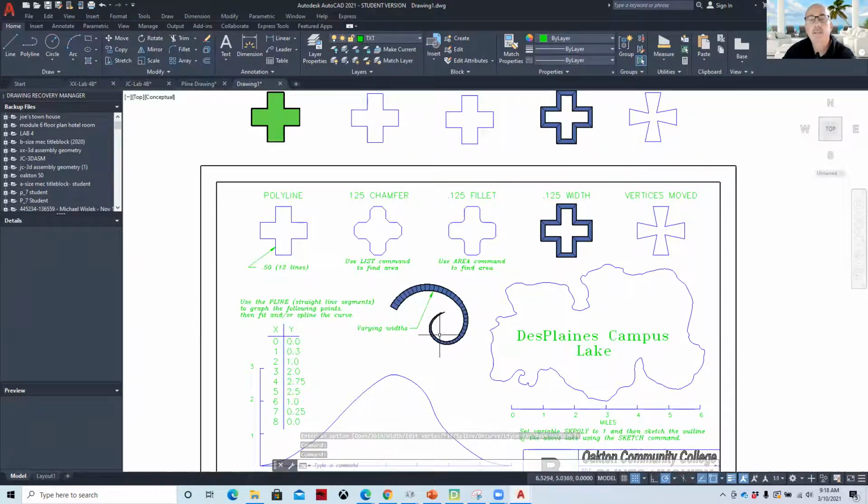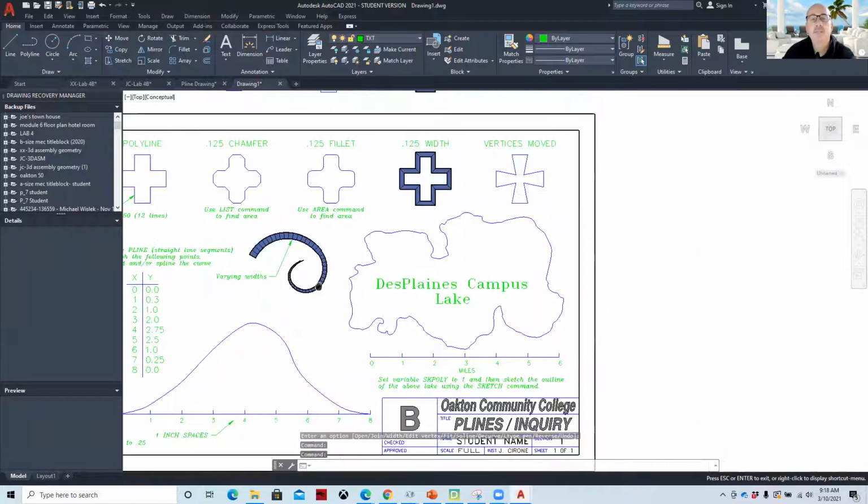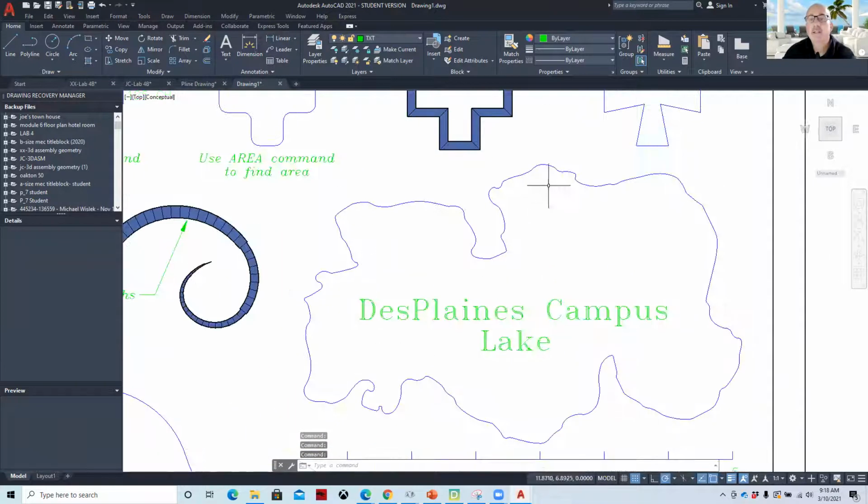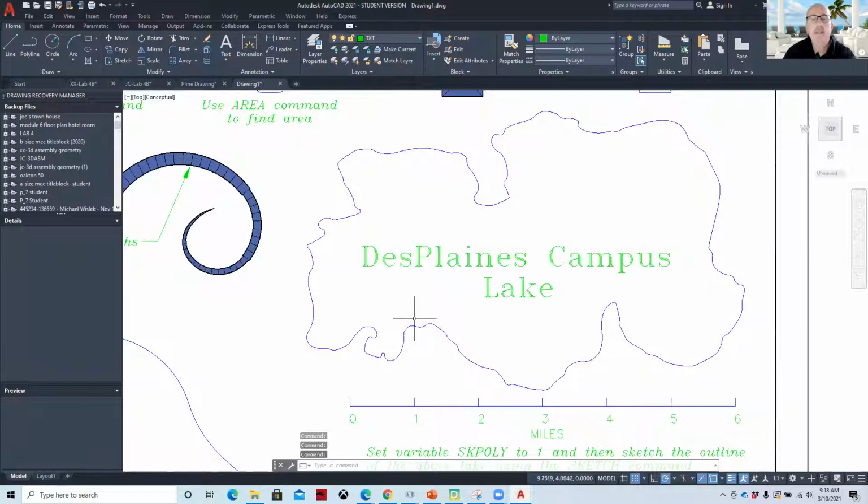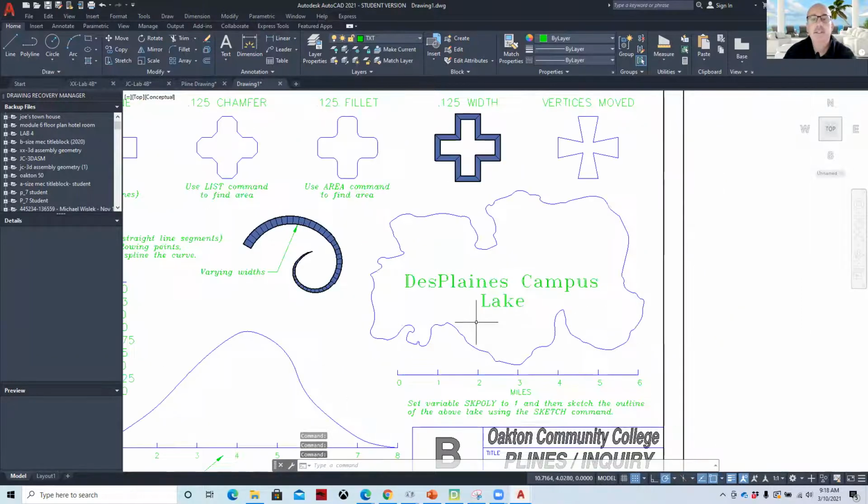This one's a little tricky. With polylines, you can use an arc option. And this is the sketch command. Map making and other details can be made using the sketch command. So if I were to say sketch, what it's going to ask me is to set the increment amount. I'm going to leave it alone at this time. Then I'll click once to put the pen down, and I'll hold that. I'll try it again, click once and drag. So this increment isn't working.